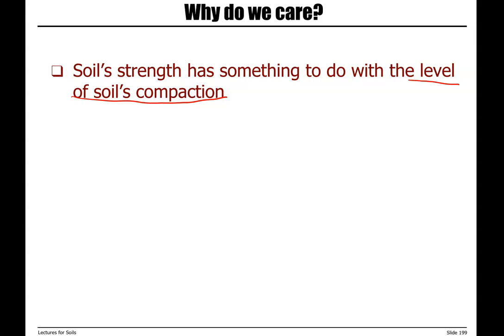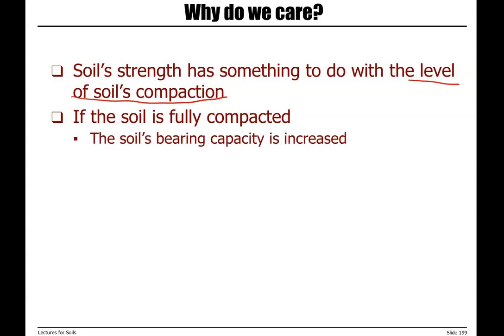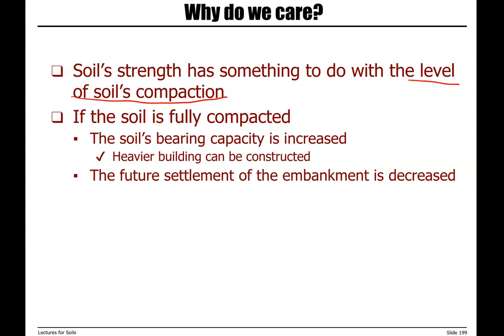If we compact our soil, and if we even fully compact our soil, it will result in an increase in the strength. The soil's bearing capacity will increase, which means that we can construct larger, heavier structures on that soil.